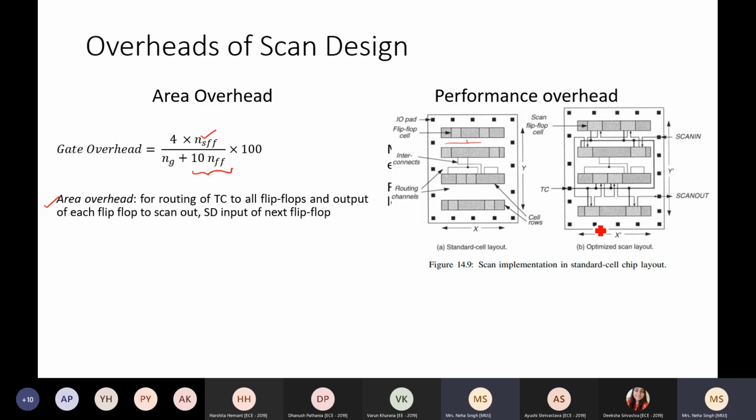Now, since I am using the scan flip-flops, the output of one flip-flop needs to be given as input to the next flip-flop, and so on. This will be input of the third flip-flop, and lastly I'll get some scan out. So the first thing that I do is I implement the basic logic of my D flip-flop, then add the multiplexer so that I convert it into scan chain.